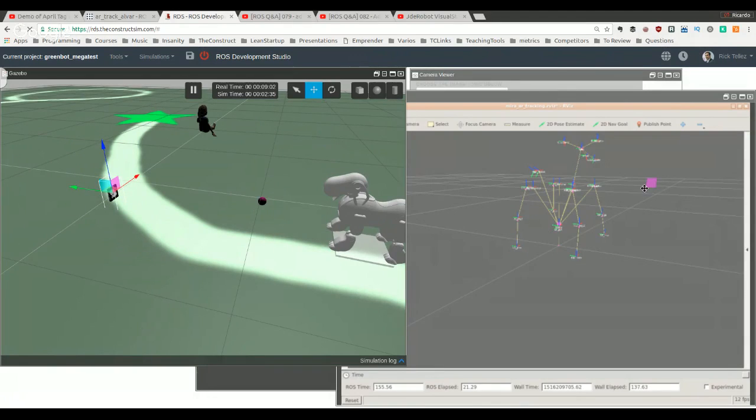And now the detection should change to a closer one. When you select this in Gazebo, the actual position is not set until you remove the movement arrows by pressing here. So now you should see, yes, you have seen the change in the position, okay? I'm going to also move it in another direction. Then it should move, yes. Okay, so far so good.